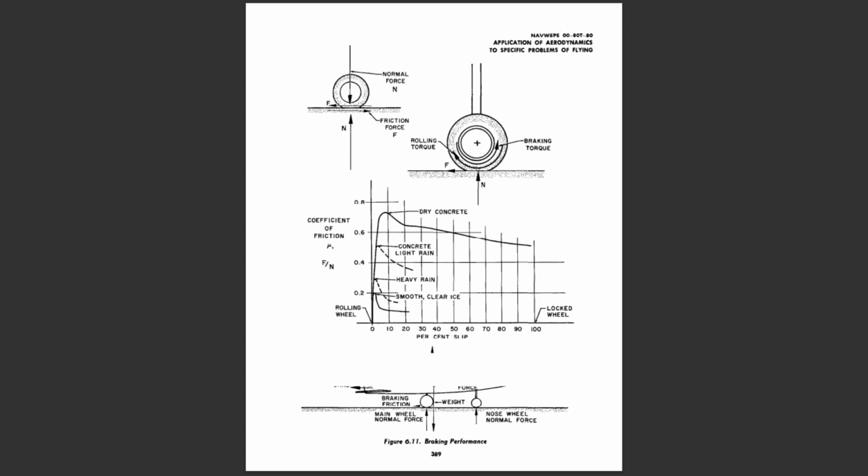Thus, once skid begins, a reduction in friction force and rolling torque must be met with a reduction in braking torque, otherwise the wheel will decelerate and lock. This is an important factor to consider in braking technique, because the skidding tire surface on the locked wheel produces considerably less retarding force than when at the incipient skid condition, which causes the peak coefficient of friction.